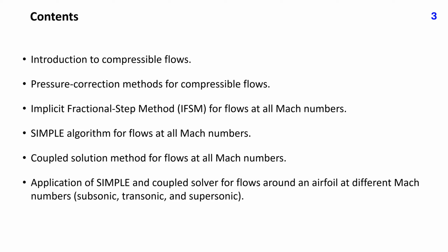Next, coupled solution methods for the computation of flows at all Mach numbers are briefly described. They have some advantages compared to the methods just mentioned when computing steady-state flows. Commercial CFD codes ANSYS Fluent and Simcenter STAR-CCM+ offer such a solver, which also works for both incompressible and compressible flows. Finally, the application of SIMPLE and coupled solvers in Simcenter STAR-CCM+ software for inviscid flows around an airfoil at different Mach numbers, subsonic, transonic, and supersonic, is presented to demonstrate the main features of these solution methods.